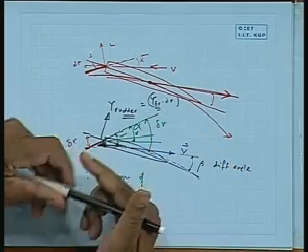So, the essential point is that you can ultimately find out the rudder force coming in the direction y and in the direction x by simply taking a geometrical consideration, finding out geometrically what my actual angle of attack is, and then resolving the forces along the desired direction.